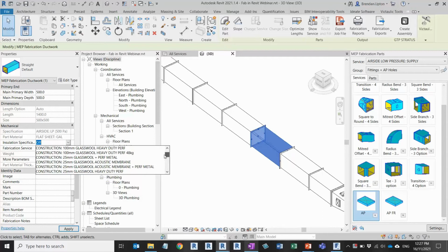So you can see, first of all, the grouping: there's a list of construction ones, and then if I scroll down the list, you can see there's a list of design ones. So this has been built now with both workflows in mind. The construction installation specs here will be working off the metal size, and the design ones will be working off the airway side. So depending on what you're doing, what you need, you can pick either one of those. And you can see further to that we've logically named these with the material, the sizing, etc. So it's all nice and neatly laid out, okay, and quite user-friendly.